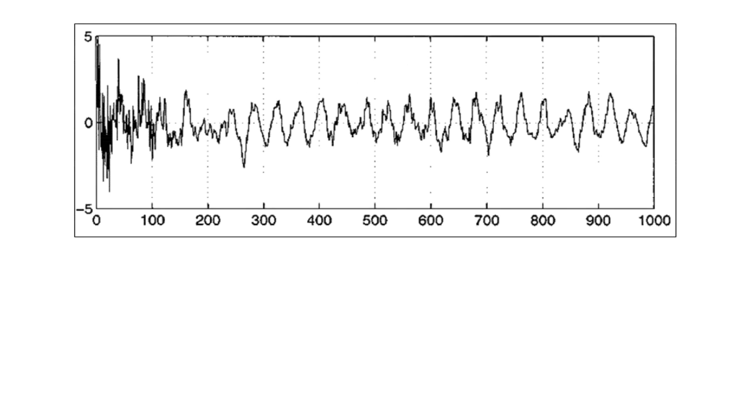So as we see the performance here, the performance of the adaptive noise canceller is not so significantly affected by the non-stationarity of the noise here. Now in this case, the success of this particular operation with the use of the adaptive noise canceller is because of the availability of the reference signal V2 of n that we have utilized for the estimation of the additive noise denoted by V1 of n to be cancelled out here.